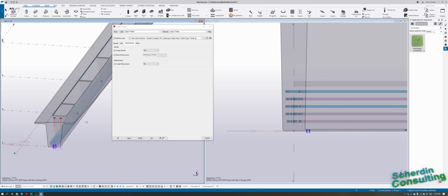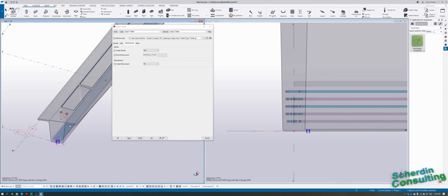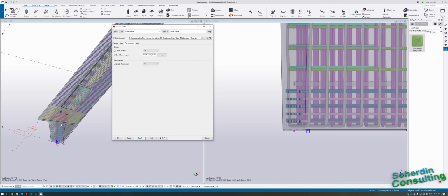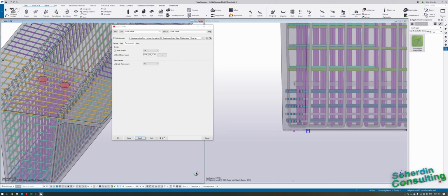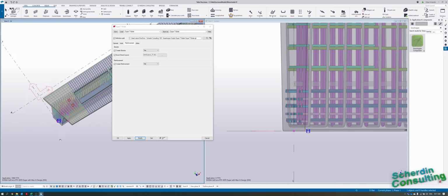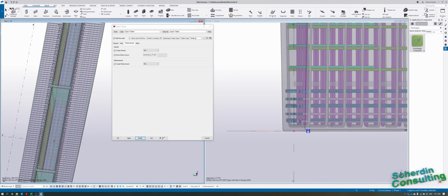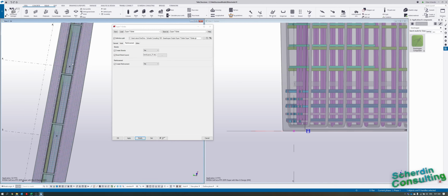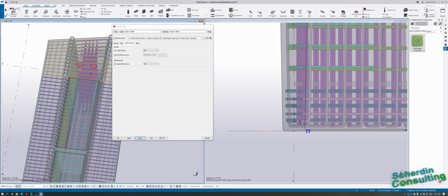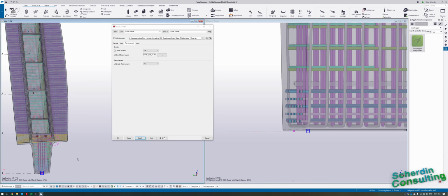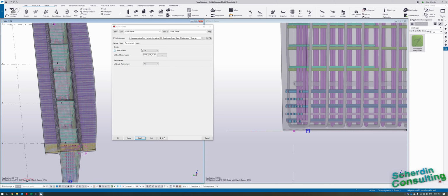We can also add the reinforcement. All of this should be so defined that you can actually just have, do you want to create reinforcement? But obviously you can make it whatever suits you. So pretty much the whole girder is reinforced. You can see that we're flaring the bars at the ends. We've got bars in between each of these voids and under them as well, and then special bars at the end. And these all adapt with changes to the geometry.